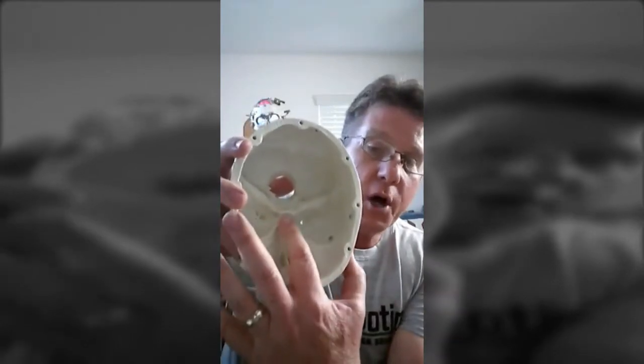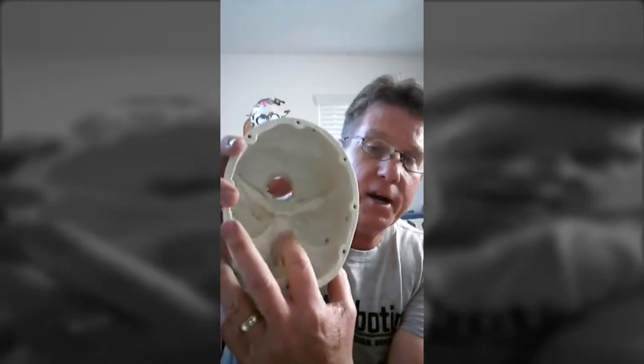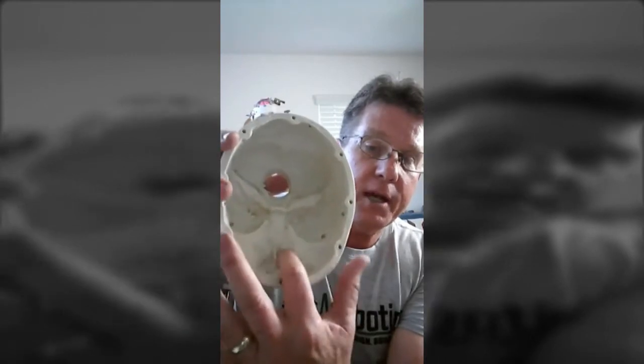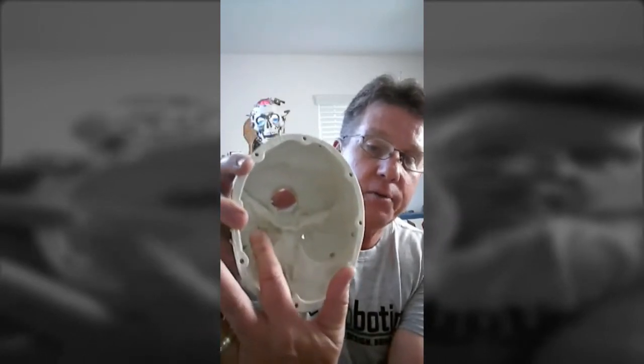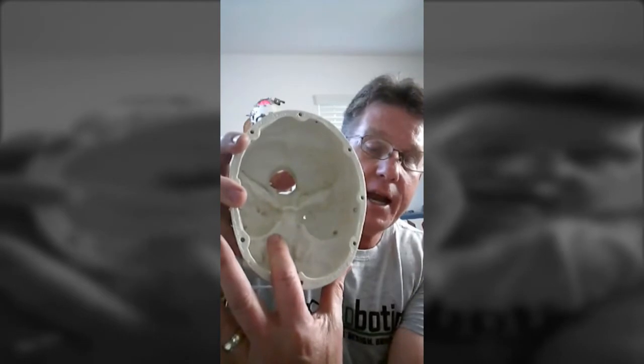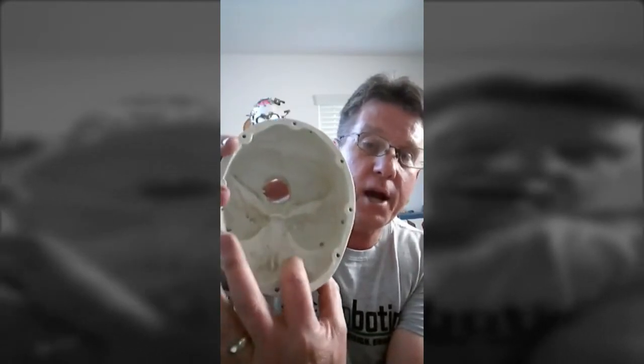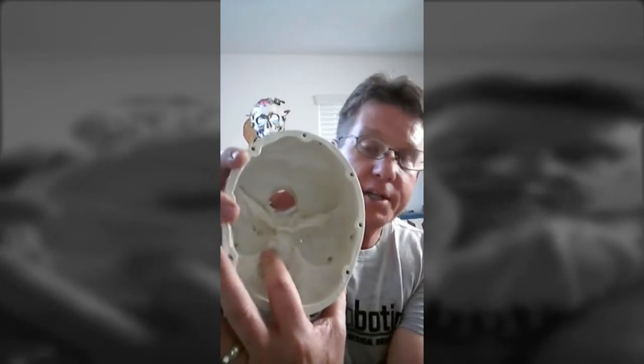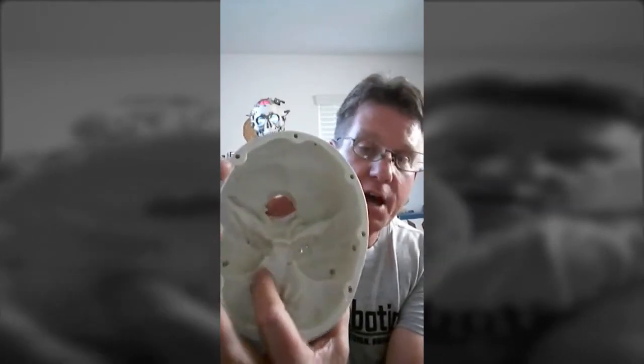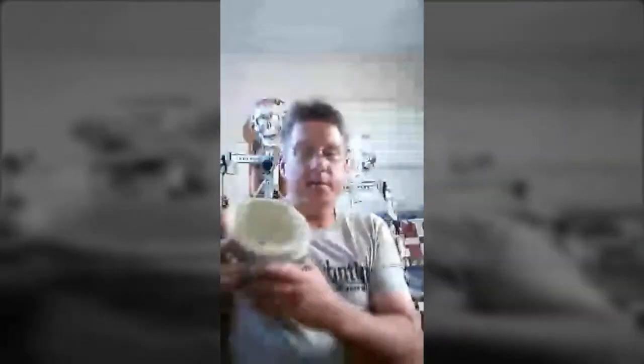So I'll usually place my bracket in there and then take a black Sharpie and mark the outline of my bracket where it's going to need to go. Then take a Dremel with a grinding bit and grind that out until you get a nice flat surface for your bracket. Okay, everybody see that? If you guys have any questions as we're going along, post them in the comments. I'll try and follow along and catch those as we go.